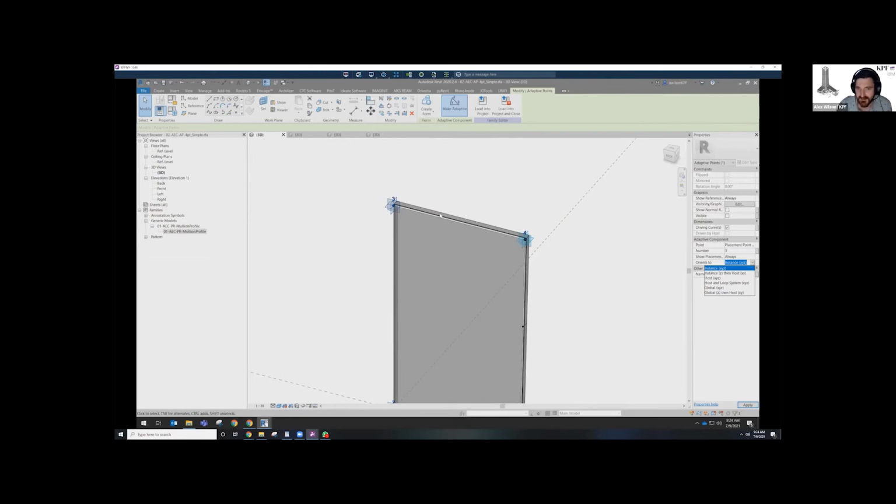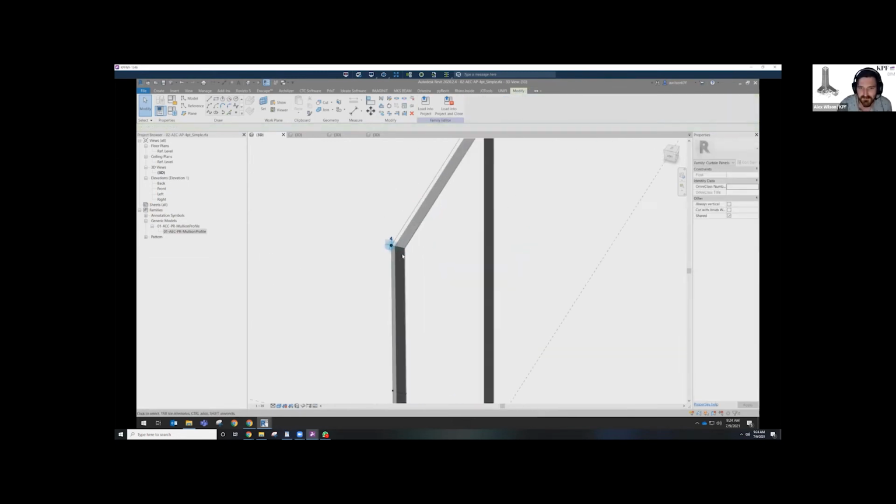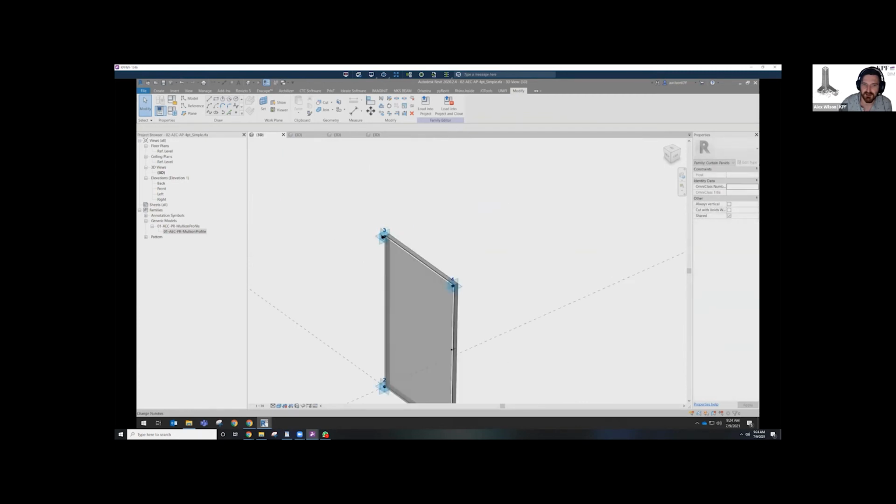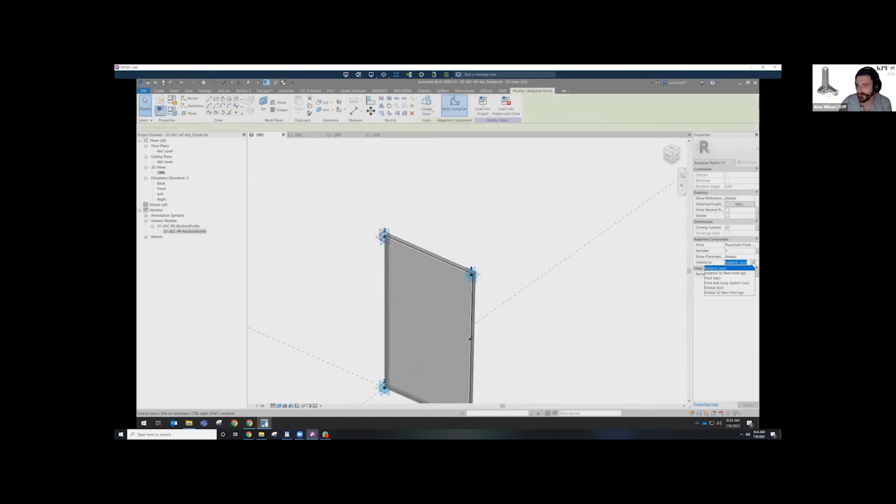It can be slightly problematic at those times. So if you are having a little bit of problems, definitely look at the style of your point, the orient of your point. Maybe look at flipping these around, trying host XYZ, trying global XYZ. I've found that if you flip between the instance and the host here, these ones don't perform very well. Ultimately, global Z and host XY is what you would like, because then it respects the vertical height but orients to the facade.